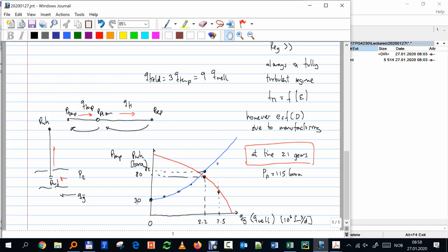Now I'm asking, if there is no choke, how should these two pressures be? And you gave me the answer before. Equal, right? So that means the only point where this system, if I put them together, will be able to operate is exactly here, right? Which is a bit below 2.2, okay? Which tells you I have to reduce the rate of the field.